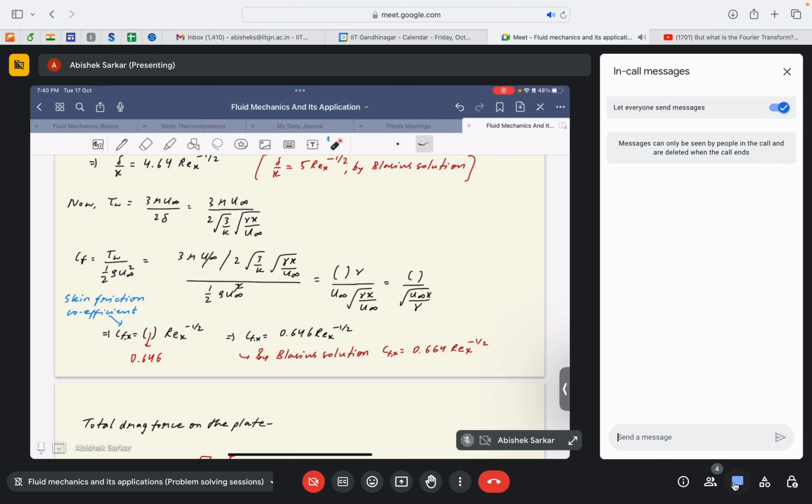Okay, and it's also observed that beyond certain orders, I guess the standard is third order, but beyond third order, there is not much variation in the results obtained from the integral methods. So third order is, I guess, the most standard one followed in the integral methods. By default, if you're solving an equation, unless told otherwise, and if they're expecting highly accurate results, the default answer should be a third order or third degree or a cubic velocity profile.